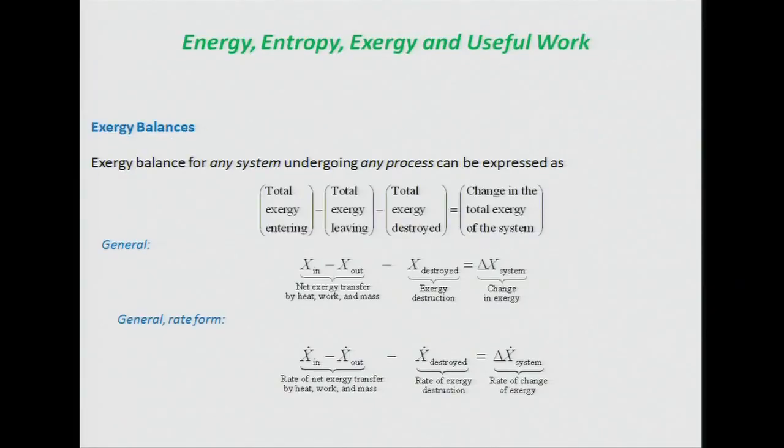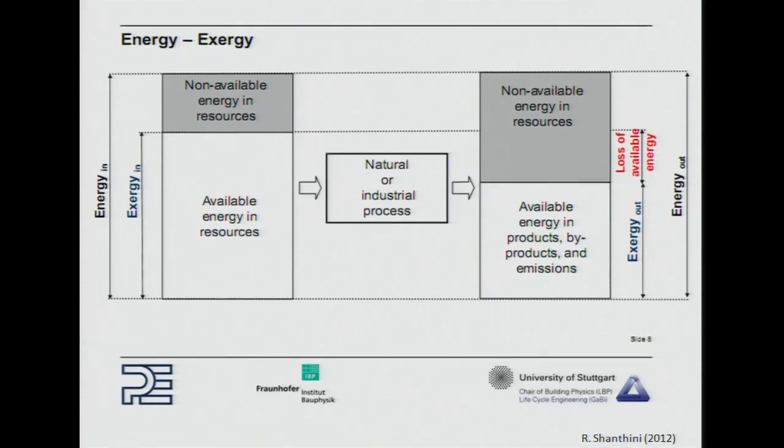Okay? Same kinds of rules that we apply to do the balances, so I won't drag you through all that. But if you look at the difference between the exergy entering and leaving a system, you subtract from that the exergy destroyed, that'll be the total exergy change in the system. Okay? And you just write that in any form you want. So again, just to reinforce the point,